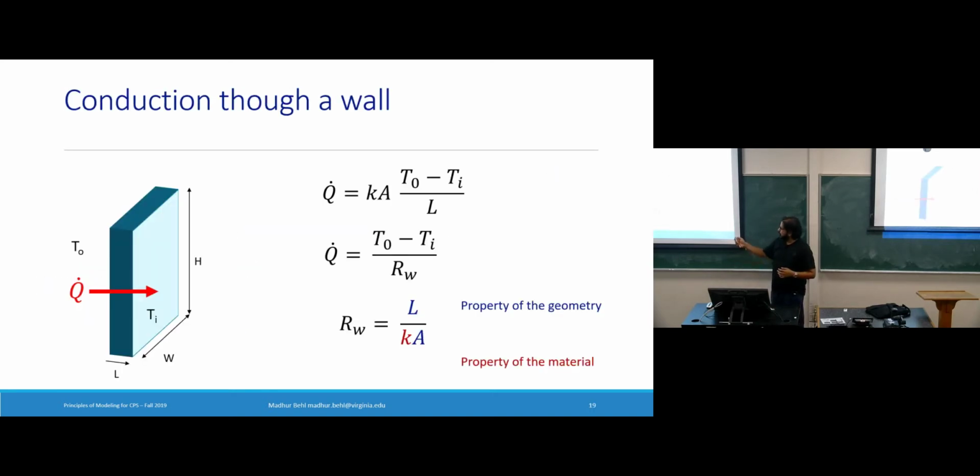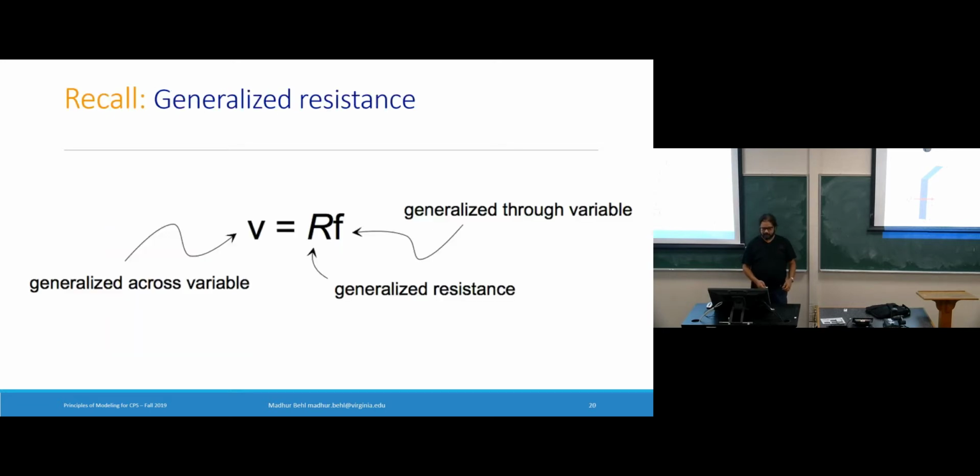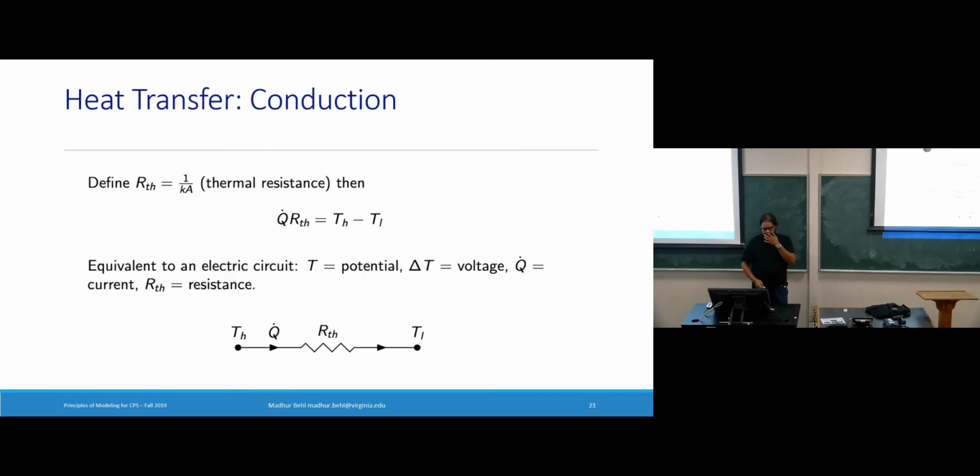Okay. So this is really what it boils down to, right? We will use time and again this equation to describe heat flow through a single surface. Right now, you can think of this wall as existing in isolation. We don't really know whether there's air on one side or not. We can describe the heat flow through the wall through conduction, right? So the key part is this is how conduction is defined with this notion of resistance.